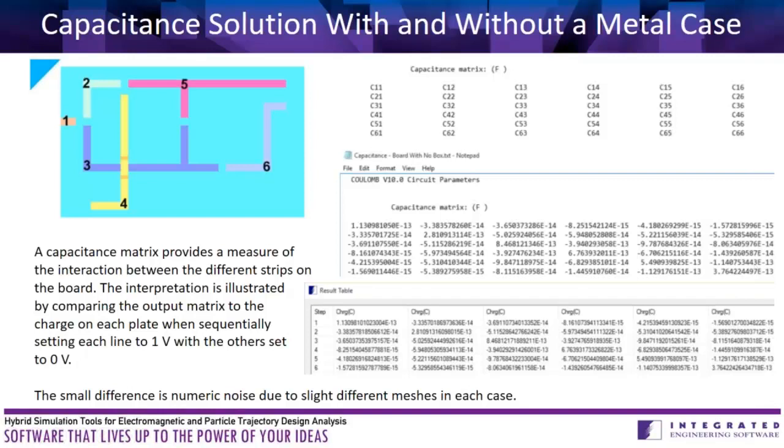So that's what your capacitance matrix lets you do, is to see at a glance how much effect each pair of conductors has on each other. You may, if you're familiar with capacitance matrices, be expecting this to be symmetric. In the case of no ground connections anywhere, where all the charge on one conductor has to appear on another because there's nowhere else for charge to go, your matrix will be symmetric.